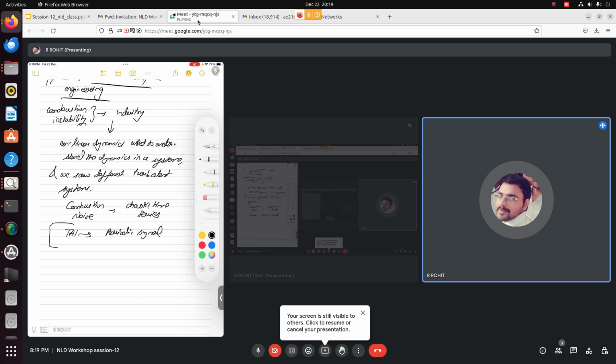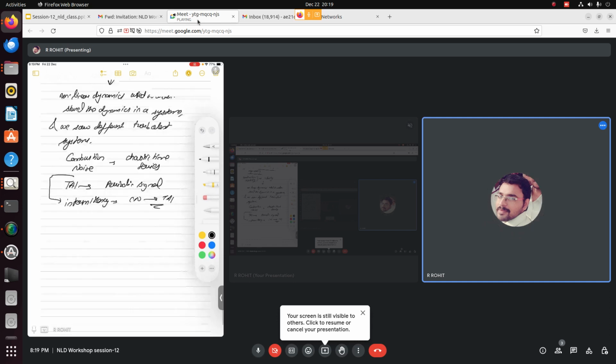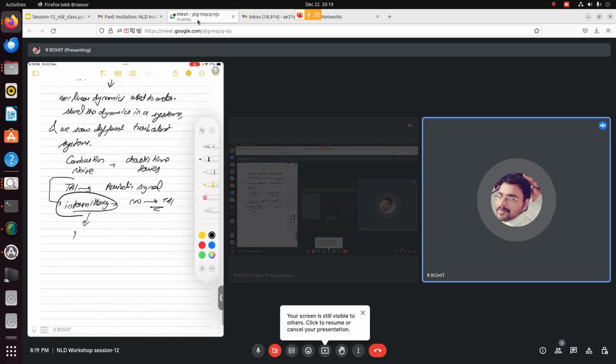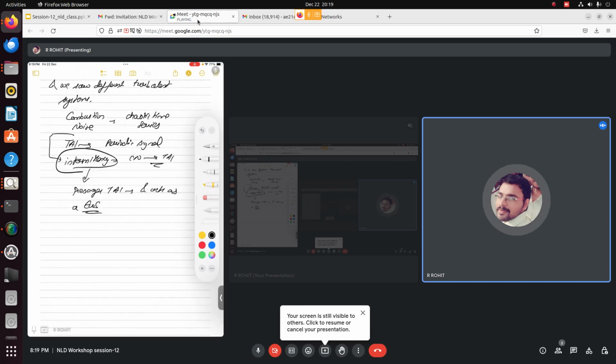And we saw an intermediate state between them called intermittency, through which the system transits from combustion noise to thermoacoustic instability. So this intermittency now presages this thermoacoustic instability and acts as an early warning signal. Once we got this early warning signal, we wanted to see qualitatively how this happens, and for a system like the Rijke tube which we showed, we saw how we got both supercritical and subcritical Hopf bifurcations